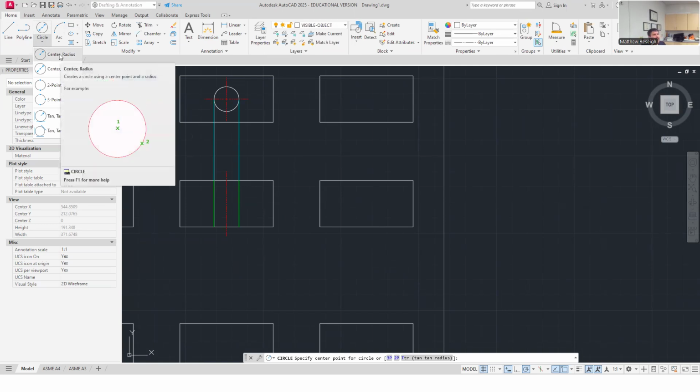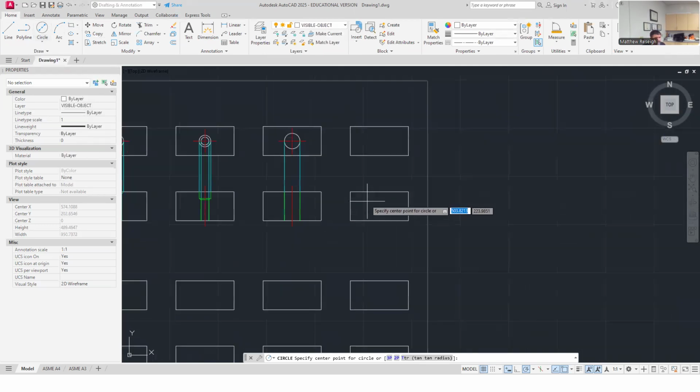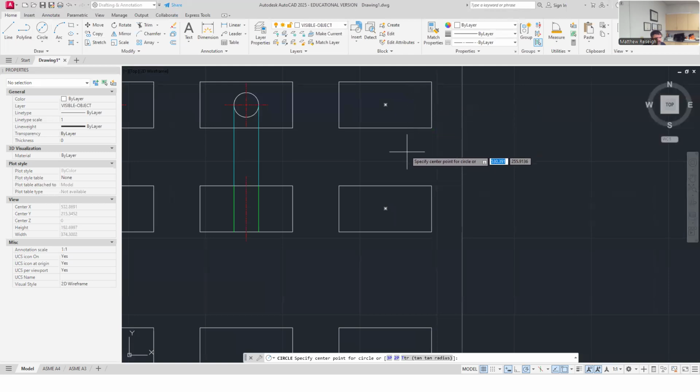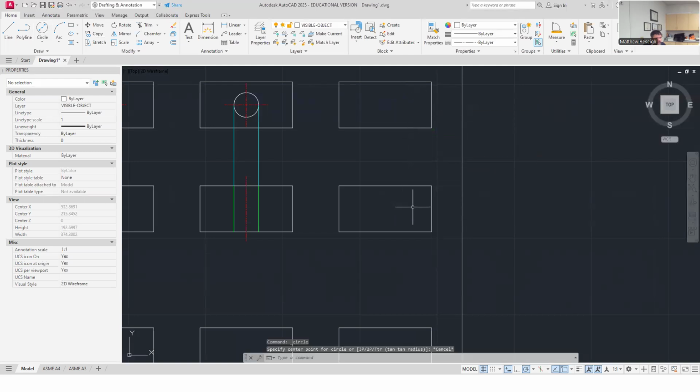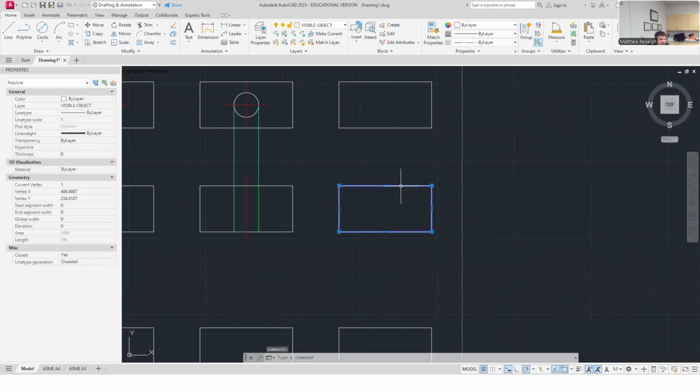Yeah, go ahead, KC. Top one with the line. Yeah, on the bottom, you don't go all the way over. You can leave the open line, use the chamfer tool, put the radius in there, and it'll automatically make it for you. So you're saying this is how you proceeded, KC? Draw a line here. The bottom one is exactly the same. Yep, how you made all the boxes before, you get rid of the top line on that box. Then you only drew over.